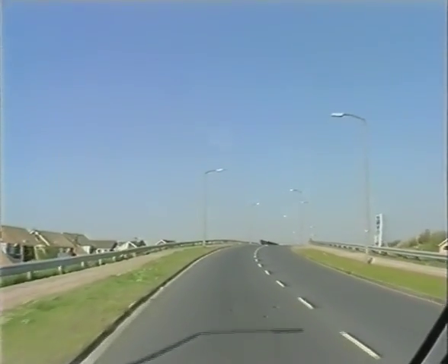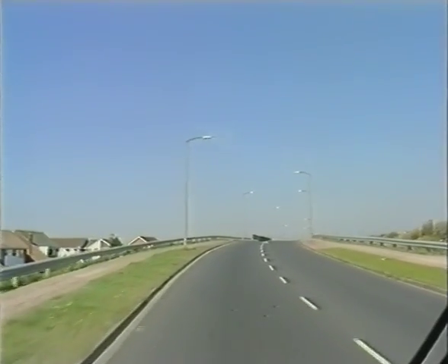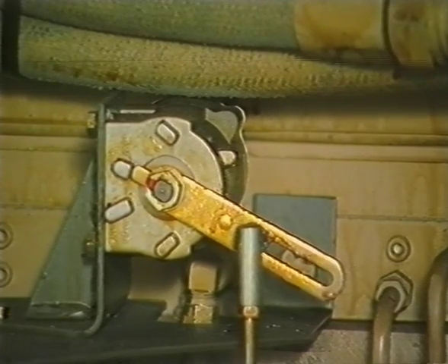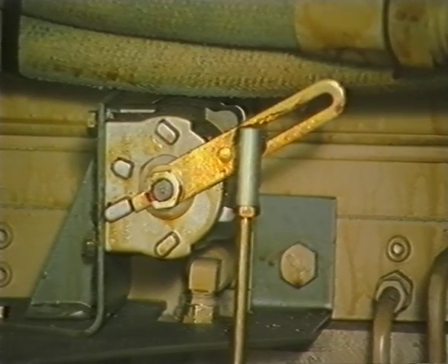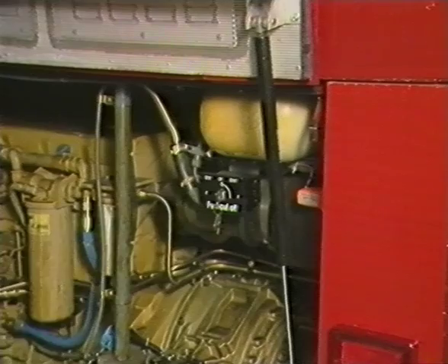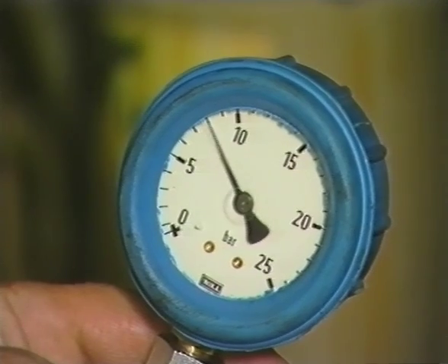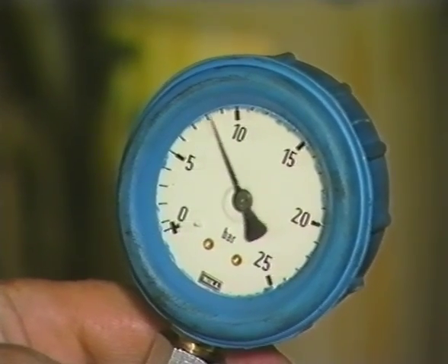On the assumption the gearbox oil level and specification is correct, check the setting of the load sender and its electrical operation. Should these items be correct, check the oil pressure. If it's low, before suspecting a hydraulic failure in the gearbox, make sure that the oil filter and seals are serviceable.